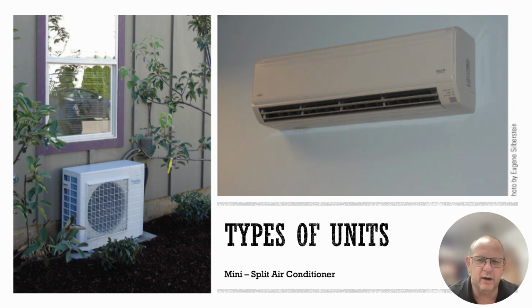These systems require precise heat gain, heat loss calculations if they were the only equipment that's going to be cooling or heating that particular facility. So we would need to do a heat loss of that particular room or that particular addition that was going in there, and then install our mini split application in that area.